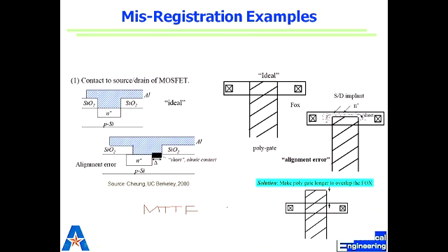Those tricks may sometimes be overshooting a feature size, making a feature bigger, or putting some boxes and edges so that when we register it, we get a sharp corner. We might also place some dummy features somewhere and expose them just to have a uniform process going on. There are many things we do to have a good registration. We'll look at those next Tuesday.